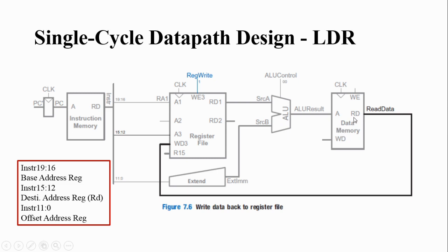So whatever data is present in that address will be sent out through RD. That content you are writing back to a register file, known as the RD file, which is configured by using these 4 bits, right? So the data you have given here, the register you have given here, and for performing the write, the write enable should be made 1. Finally, when you give the clock, on the rising edge of the clock, the data you have given here will be written to the destination register. That is how you are performing the load operation.